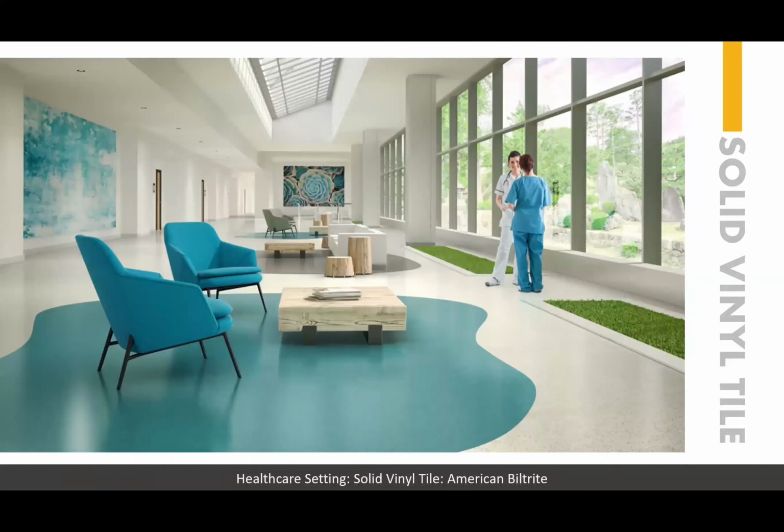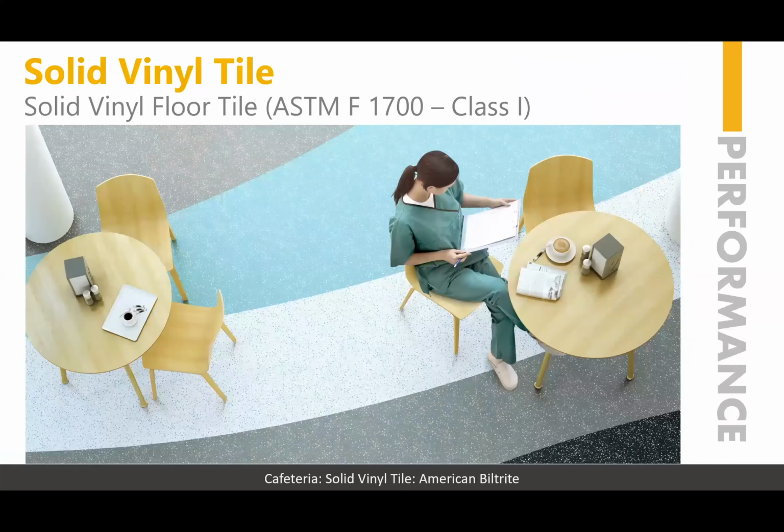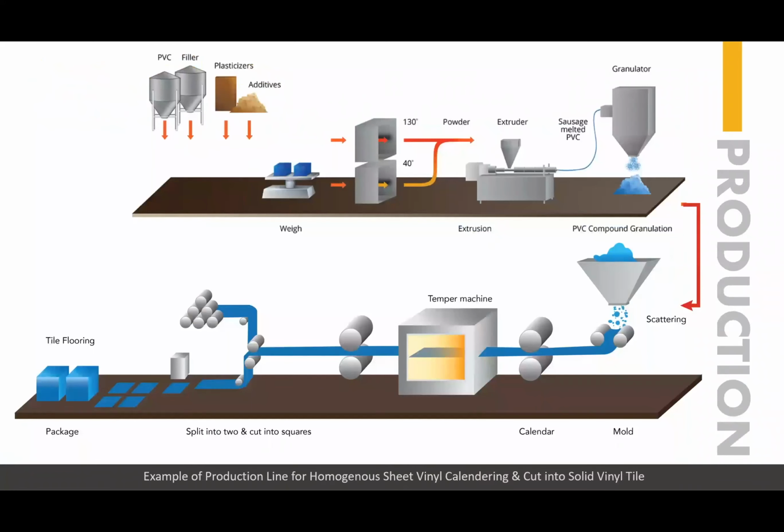Solid vinyl tile is another category, although others fall within some of the same ASTM methods, just in a different method or class. So solid vinyl performance is ASTM F1700 in class 1. So there's two ways that you can make solid vinyl tile. One is the homogeneous sheet calendaring that we showed you earlier for the sheet product, and that sheet product is then cut into squares and into tiles. So that's one way of doing production for solid vinyl tile.